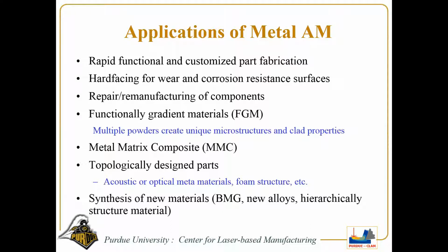The problem is that in the traditional way, they could not do this, so they make only 10 or 12 different shapes, and you have to put that in the body, and obviously it's not going to match perfectly. Now, with metal additive manufacturing, a doctor scans someone's bone shape, and then you can fabricate the implant to the exact same shape the patient needs. So basically, what we call mass customized parts. You can produce parts as needed to the exact specification.